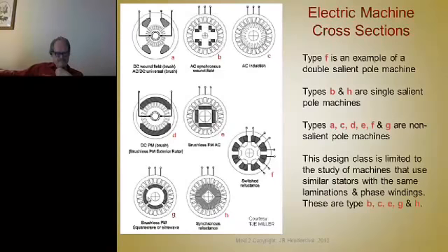Now, take this same motor here with the magnets on the surface. This is an SPM, surface-mounted magnets, we call those. If you take the rotor core and put slots inside of it, instead of having the magnets on the surface, you stick them on the inside. That's now known as a brushless permanent magnet AC machine, or permanent magnet synchronous machine. And so you get torque from the magnets, but you have some little steel poles in between the magnet poles here, and you can vary how big those are.